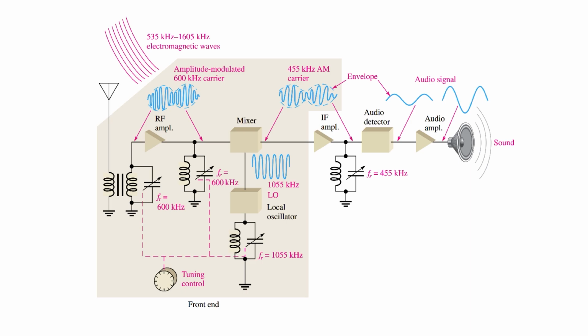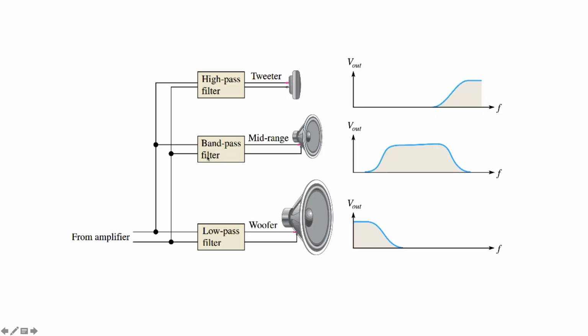For example, a first-order filter, such as those we have been studying, has a slope of 20 decibels per decade in the gain plot. Adding a second filter makes it a second-order filter and increases the slope by twice as much, to 40 decibels per decade.